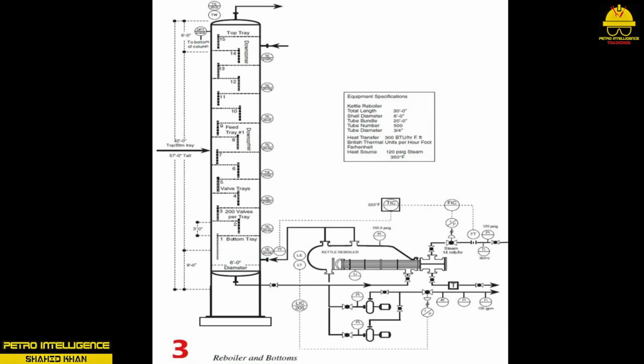25. Watch online analyzers for top and bottom purity. Put online when good sample comes back from lab. The following information is a typical example of all of the data, process variables, and so forth recorded, collected, or observed by a process technician.